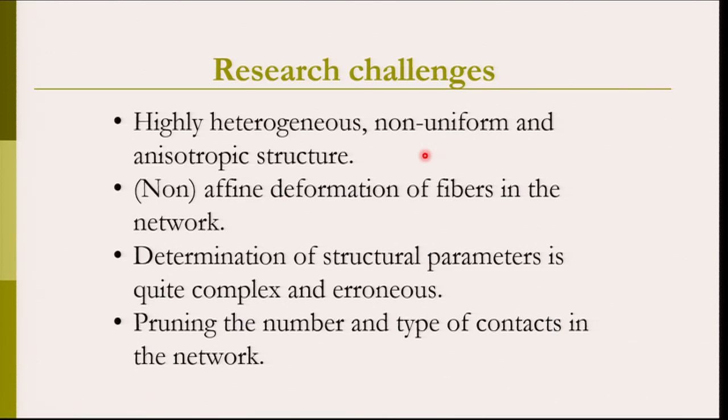For example, in a thermally bonded nonwoven, it may happen that certain fibers are fused in nature, but certain fibers have not been fused and there is a frictional fiber to fiber contact existing in the structure. So, it is a combination of both the frictional contacts and fused fiber contacts.